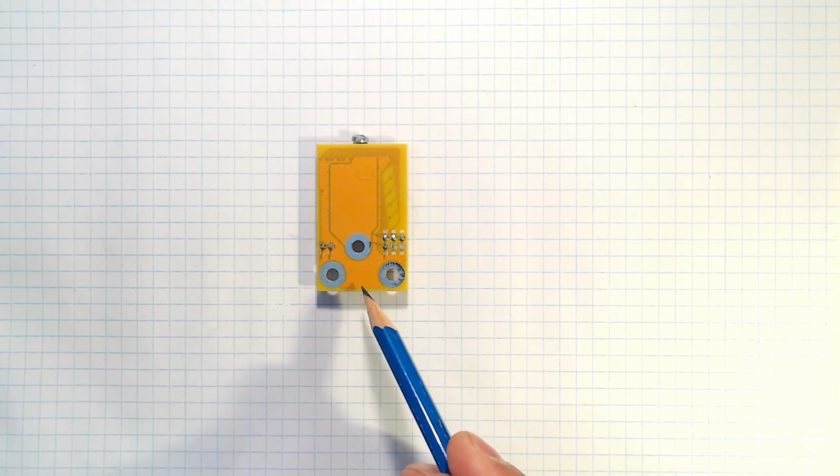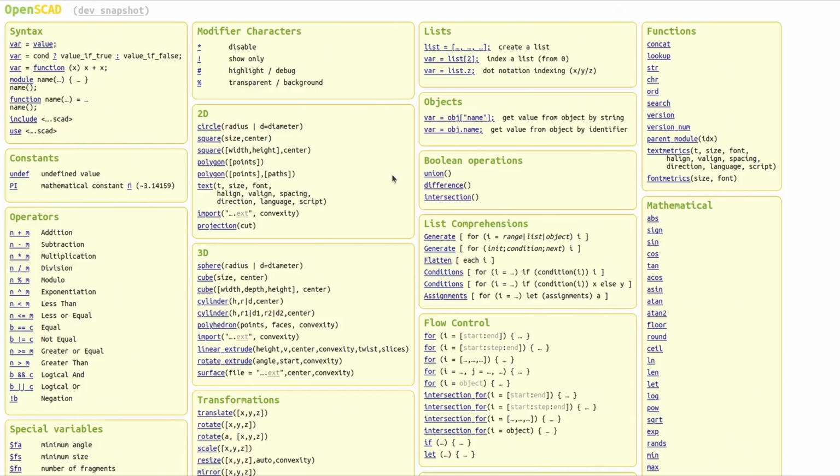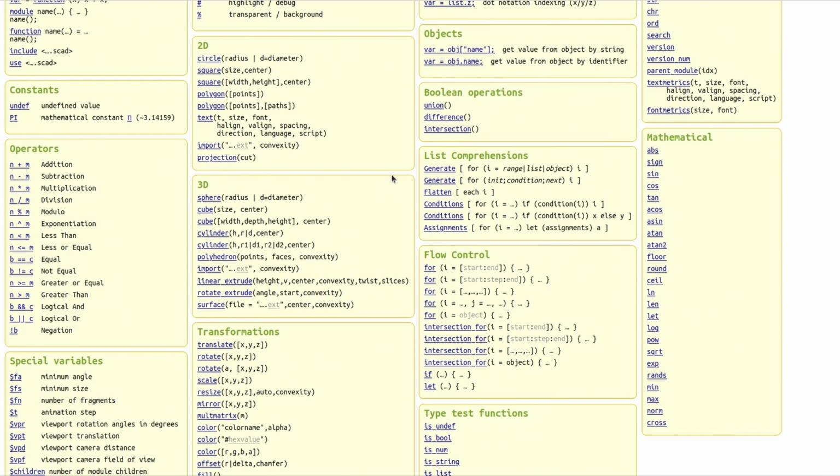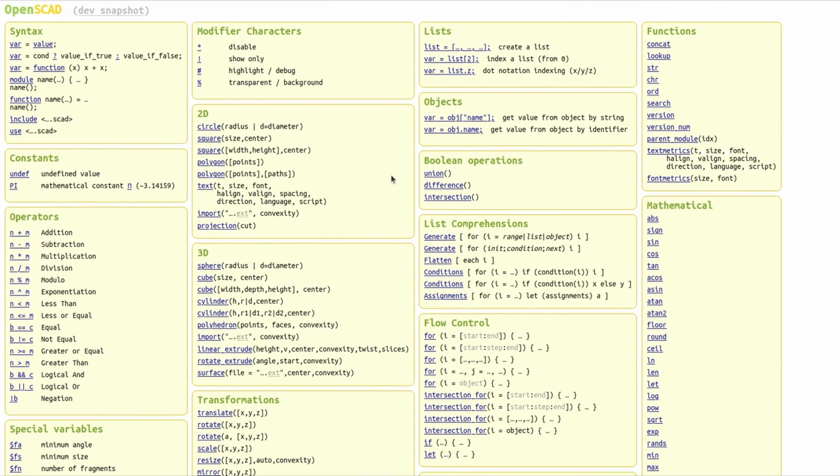With the thermal hole complete, we can now move on to the terminal guides, which are the openings to allow attachments to these terminals. Now we could take the approach that we've been taking so far, which is to take a circle and combine it with that polygon and then cut that out of a solid, and that will give us the curve. But I'd like to try something different. I want to create an arc. However, examining the cheat sheet reveals that there is no arc function in OpenSCAD. So we're going to have to custom make it.